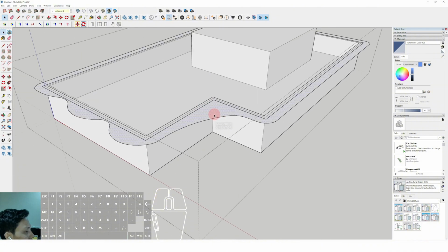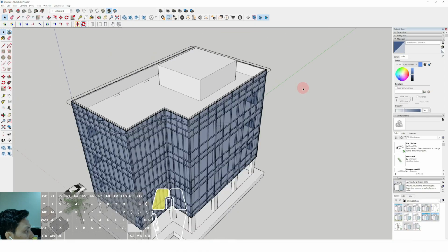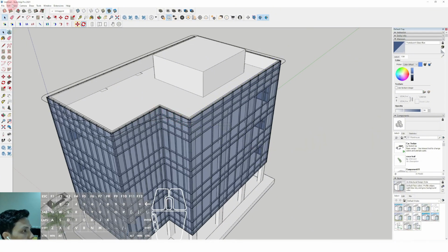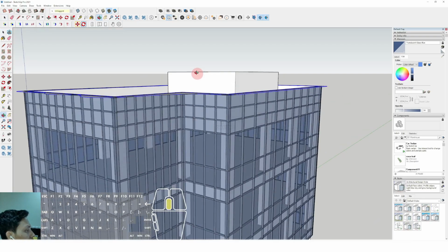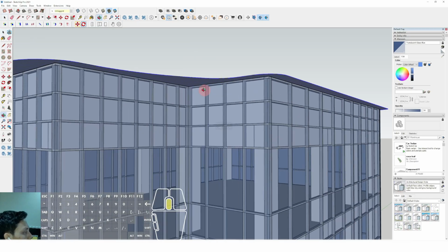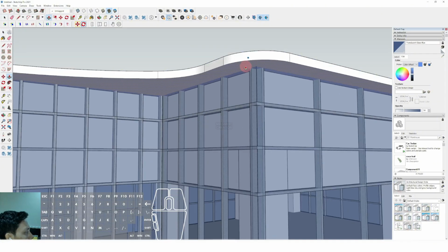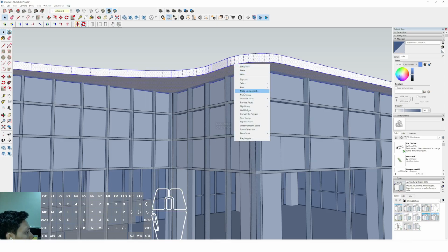Okay, just like this. Then we can click the surface and select edit, cut, exit from the group, and edit, paste in place. So it will be automatically placed and pasted based on the origin position. Then now we can push it down around 200 millimeter and double click, make component, create.